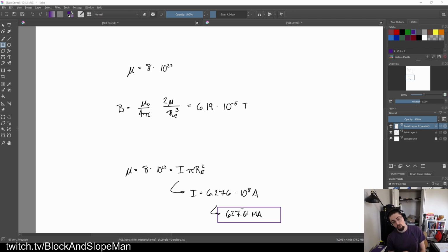And this is a very useful trick, actually. This is why oftentimes you'll see a bunch of different coils with a lot of smaller wires rather than larger wires. Because while the larger wires can deal with more current a little bit more easily, the smaller wires, you can stack them a lot closer together and you can oftentimes recreate these dipole moments in a really massive fashion with the same amount of space.